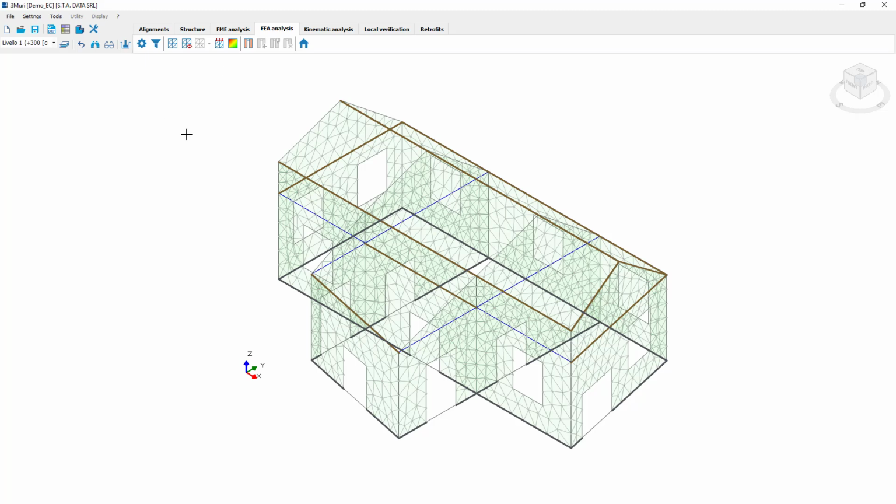On the other hand, the FEM approach is going to be very useful in the case of highly irregular distributions of openings along walls and height, a significant presence of walls that don't have any openings, and for example, when I wish to examine more precisely the distribution of floor loads in the masonry, but this means accepting longer calculation times. And of course, I am willing to go into detailed verifications of various masonry piers in order to optimize the verification as closely as possible to reality.